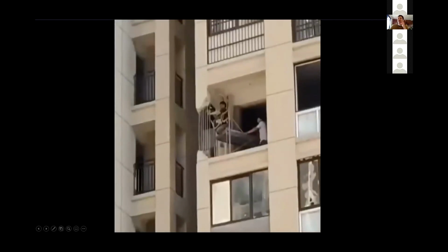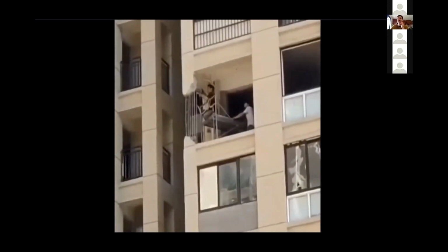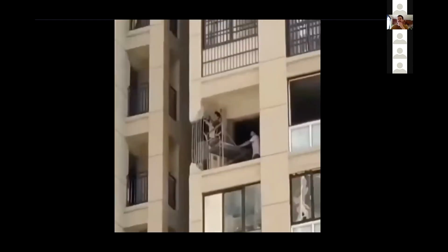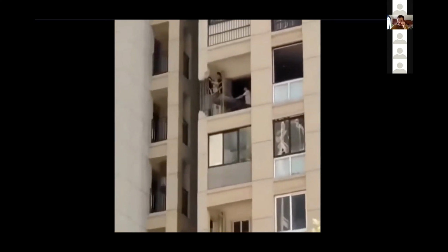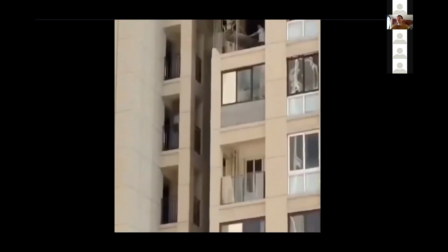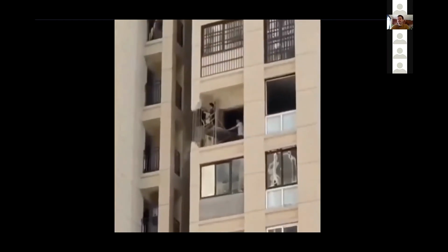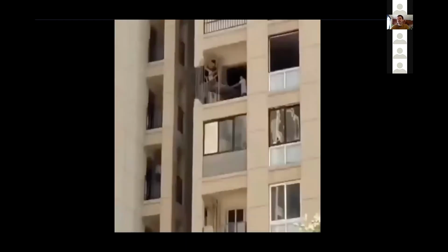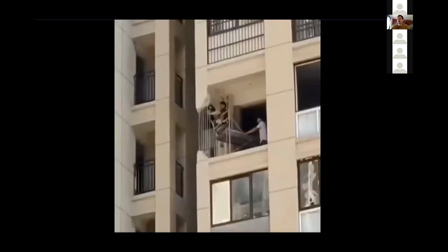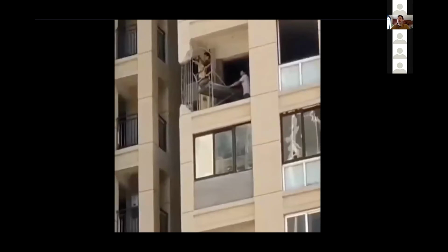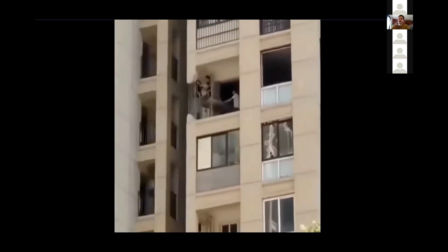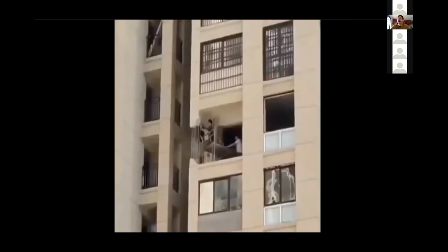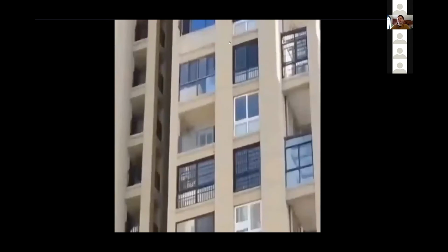This came up on my LinkedIn feed over the weekend. I don't know if anyone else saw this, but quite scary, of course, for any structural engineer, but quite good timing too for this presentation. Fortunately, it's a good example of the redundancy and robustness that this structure has. It looks like a cast in situ moment frame construction, and you've got redundant load paths where the beams can act as cantilevers as well as the columns taking tensile loads. Just scary stuff though.